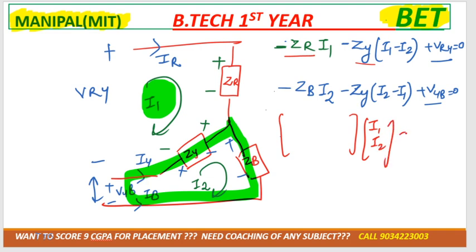I1, I2, and that goes to the right hand side. Voltage I'm taking on the right hand side: 400 angle 0, 400 angle minus 120. Solve it and tell me the coefficients of these. After solving, you will get 10 angle 0 plus 15 angle minus 30.